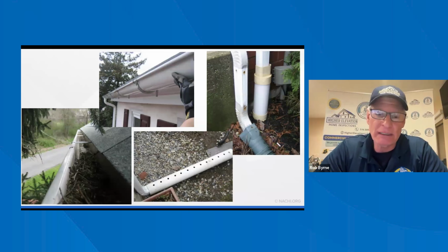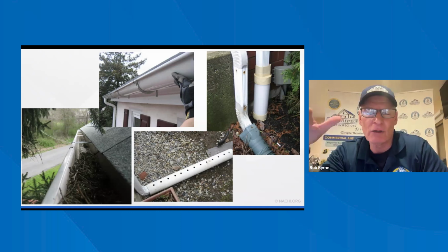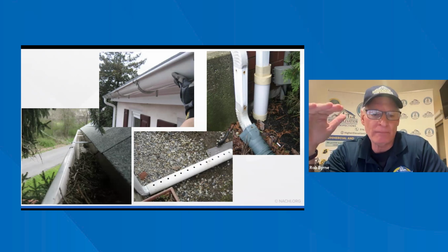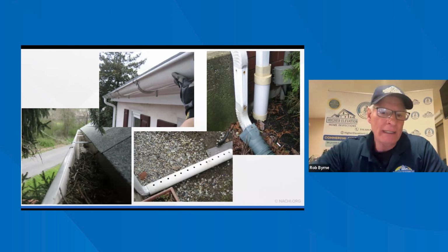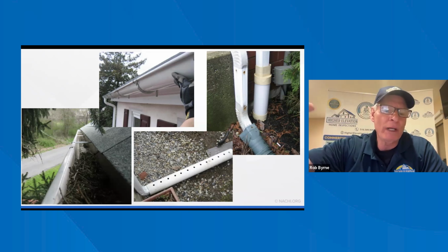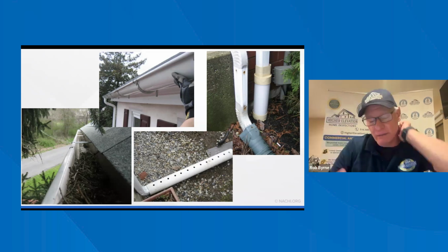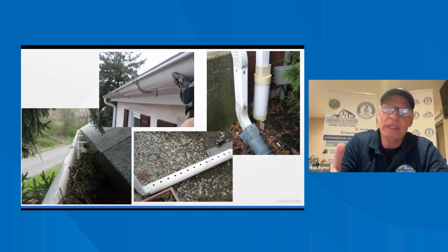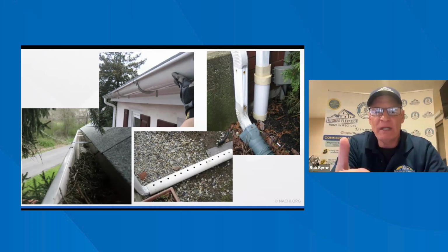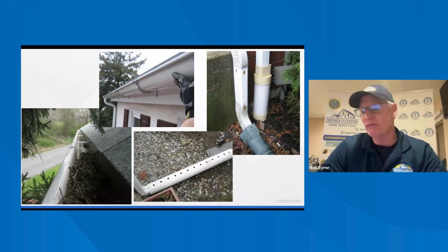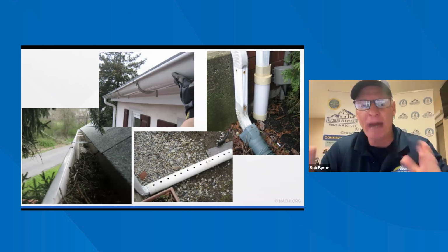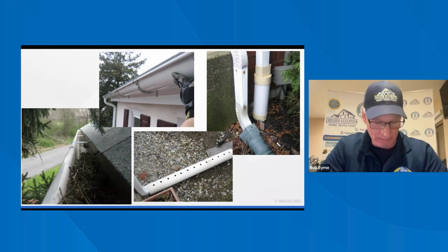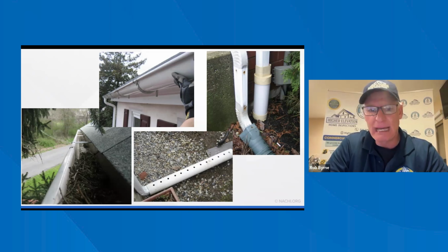It's interesting, as we just did an inspection today, and we had the same exact problem. No gutters. It was actually the garage, and it was on a setup where the garage was below, and the neighbor's yard literally went all the way up, and they had no gutters. They couldn't even get to that side, and the whole wall was pushed in because of that simple fix of getting the water away from the house. That's important. Water management. How is water being diverted away from the house?